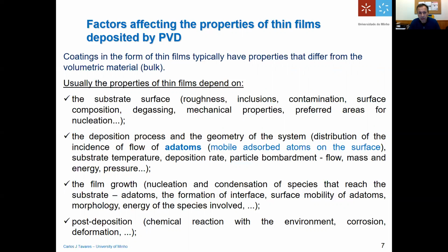If you're using vacuum methods to deposit the films, you have to avoid materials which degas. For example, if you use sputtering, before you can sputter, you have to reduce the pressure inside your sputtering vessel at least 10 to the 9th relative to atmospheric pressure, which means that you'll be working at about 10 to the minus 6 millibar before making your film.